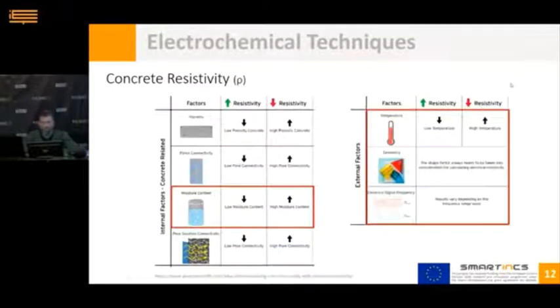However, in addition to concrete porosity, there are a number of factors that affect the resistivity measurement, most notably the water saturation degree, concrete temperature, specimen geometry, and the type of electrical signal used in the test. Many of these factors can be controlled or corrected during the tests, so that the resistivity measurement can be linked primarily with concrete porosity.